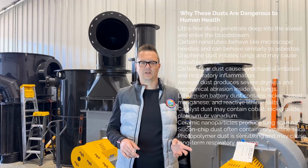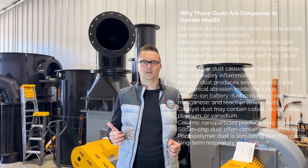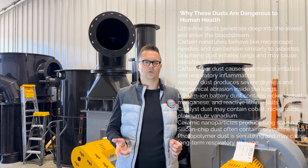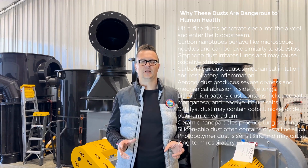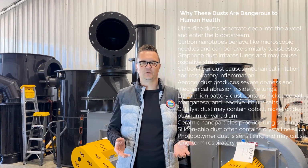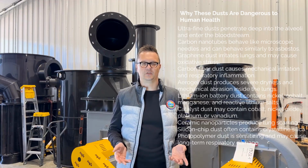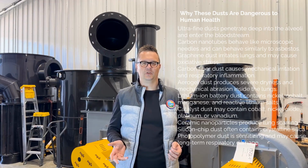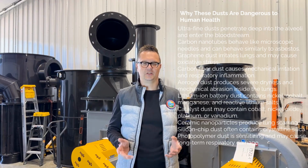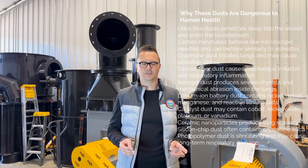Why these dusts are dangerous to human health. Each behaves differently. Ultrafine dusts penetrate deep into the alveoli and enter the bloodstream. Carbon nanotubes behave like microscopic needles and can behave similarly to asbestos. Graphene dust irritates lungs and may cause oxidative stress. Carbon fiber dust causes mechanical irritation and respiratory inflammation. Aerogel dust produces severe dryness and mechanical abrasion inside the lungs.